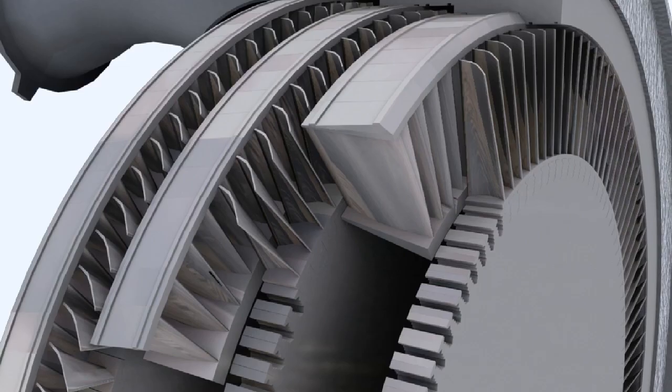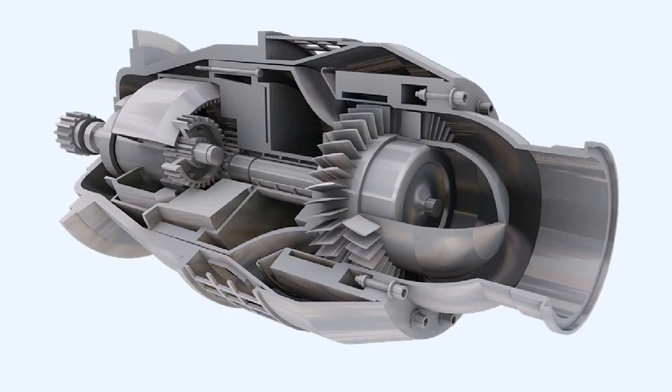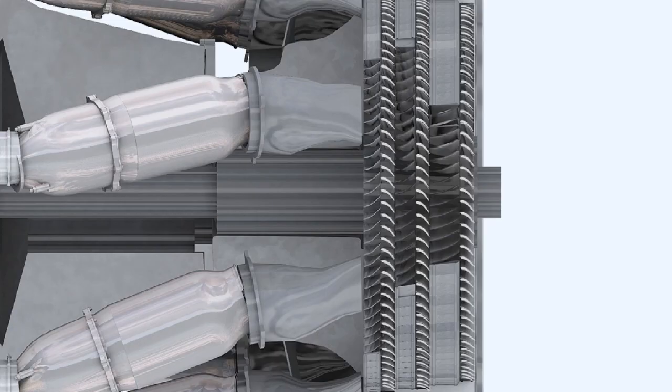Normally, gas turbine engines do not use either the pure impulse or the pure reaction type of blades. The proportion of each type of blade utilized is dependent upon the design requirements of the engine. In general, the combination impulse reaction is more commonly used. Impulse-type turbine blades are used in air starter motors. It's very rare to find pure reaction blades being used. When they are, the nozzle guide vanes are designed to divert the gas flow direction without altering the pressure of the gas.